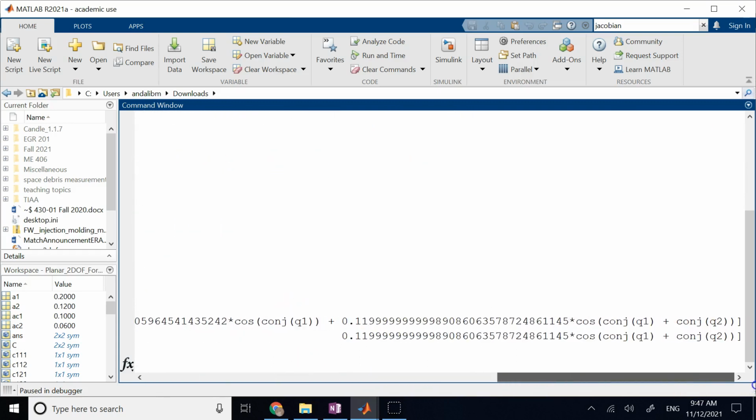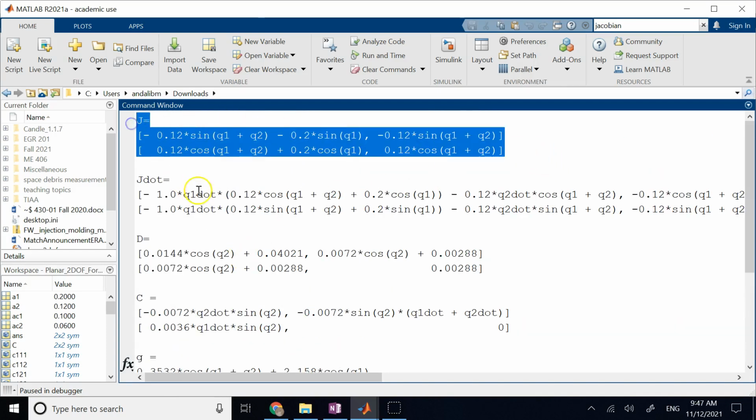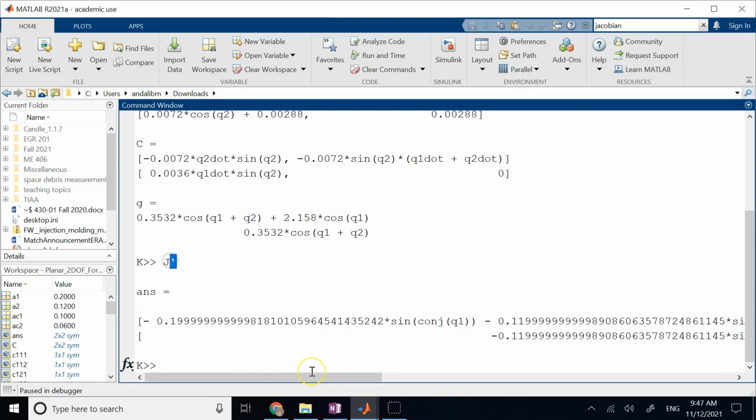Look at this. All I needed was to just transpose this matrix. And I used the quotation, but it gave me something very weird. So if you ever want to transpose, inverse is okay, but transposing a symbolic matrix, you have to use the command transpose, not the quotation.